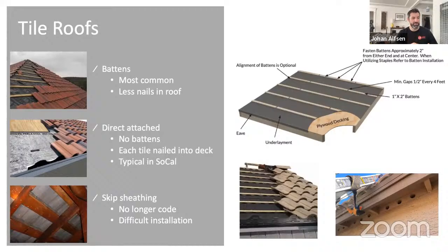So they changed the requirements to solid sheathing, underlayment, and then the tiles. The construction is important, because if you bid the job for a standard tile job, and then you get up there and you see that there is no decking, you're going to encounter a little bit more labor.